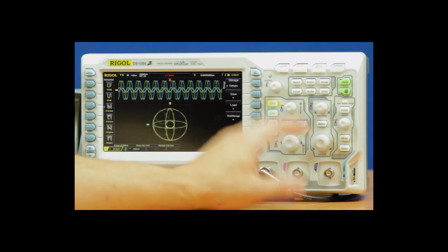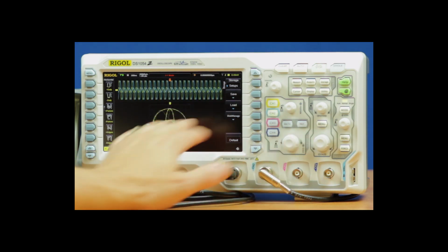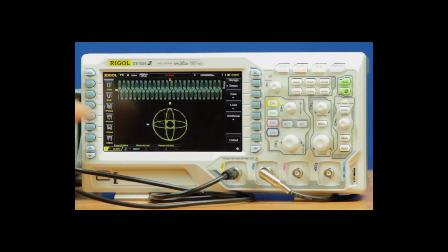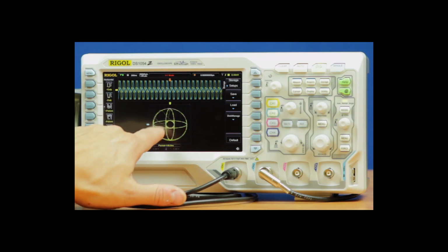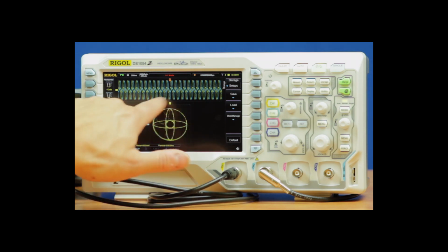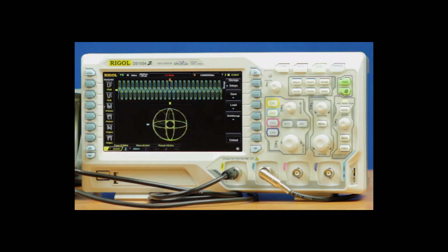The yellow channel 1 being 90 degrees before the blue. And we can tell that because of the circular nature of the XY curve. That shows you that you're one way or the other, either 90 degrees out of phase between the two channels. What's also happening is you can see the two levels of amplitude here. The inside circle being a lower amplitude, the outside circle being a higher amplitude.